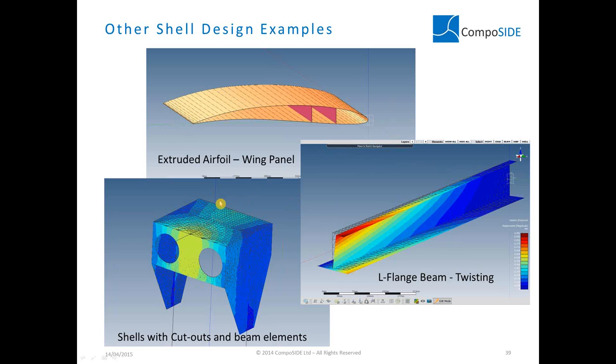Okay, there is another question if we can create holes and locally reinforce shells. And yeah, that's why we went back to the previous slide. We can create holes in shells, and you can reinforce it either by extruding the edge and adding materials to the shell, or by creating a beam here. So you can run combined models with beam elements and shell elements, which is quite a good approximation and quite often used in a design stage where you're really checking the feasibility.